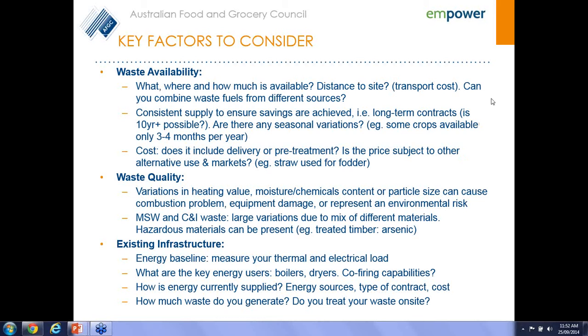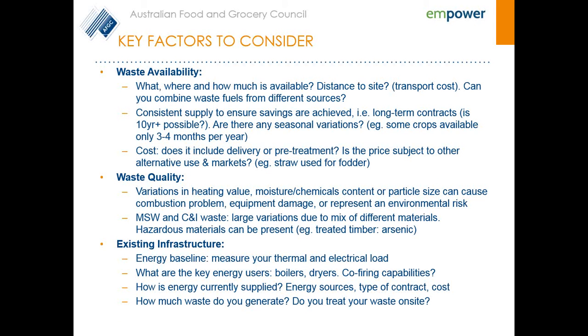The first thing is to determine the energy baseline, so quantifying what the thermal and electrical load is, because that will then allow you to size your biomass boiler or your digestion process to suit your thermal or electrical requirement, if you're thinking about putting in a cogeneration unit to supply some of the electricity.